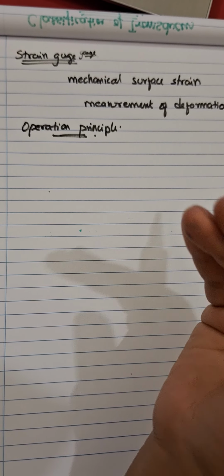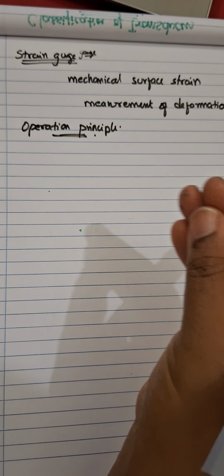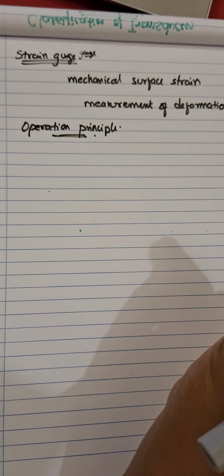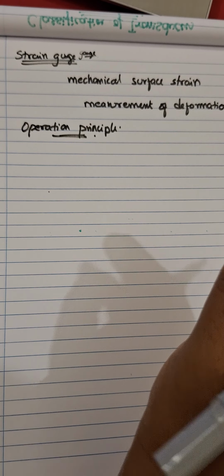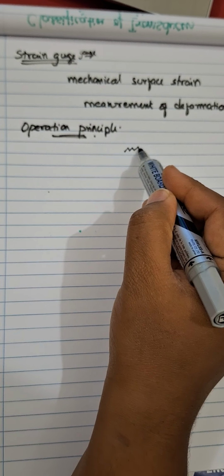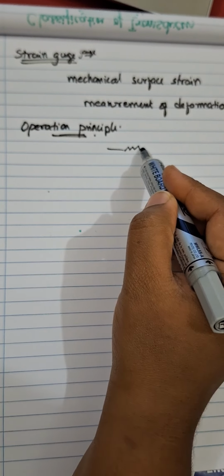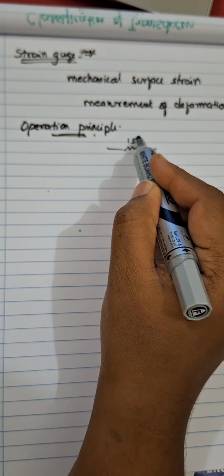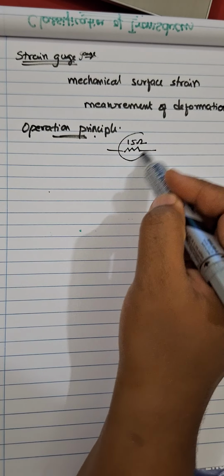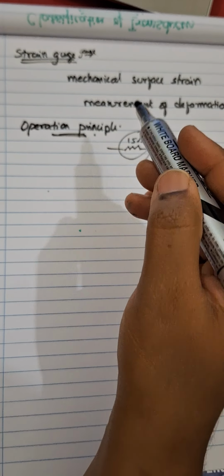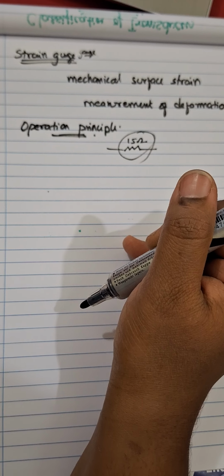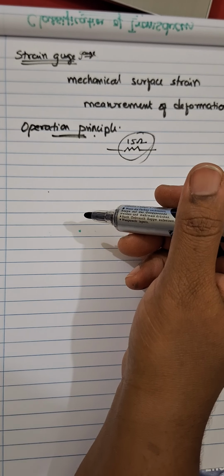At one point some resistance is changed. Usually you kept a resistance as 15 ohms, but suddenly because of over operation of the system it changed. Now you want to know the change, so you make use of bridge methods, like the Wheatstone bridge method.